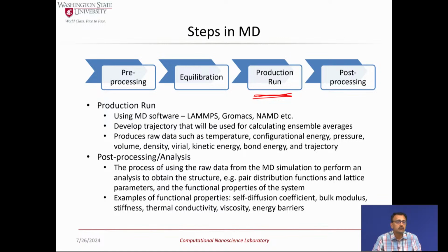Good question. So just to repeat that for everybody's benefit, the question is, what if your measured lattice parameter from experiment is different from what you get by minimizing the structure? That typically would mean your force field is not suited for that problem. So you have to look elsewhere for a force field that is able to capture your measured lattice parameter or structure that you are interested in, that particular phase, crystalline phase.